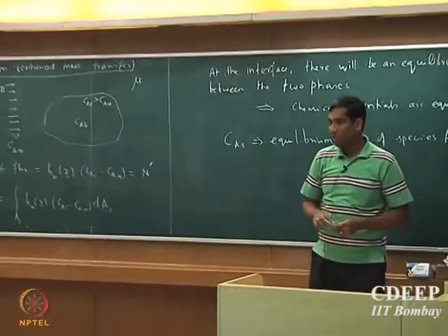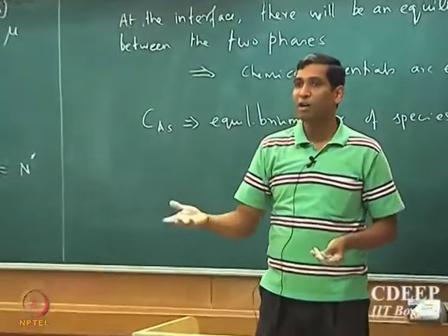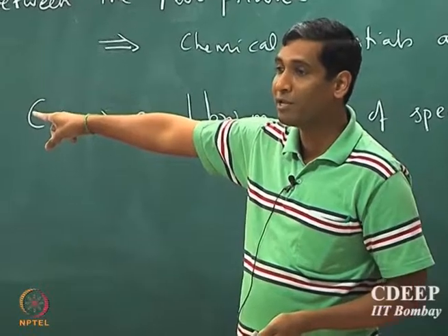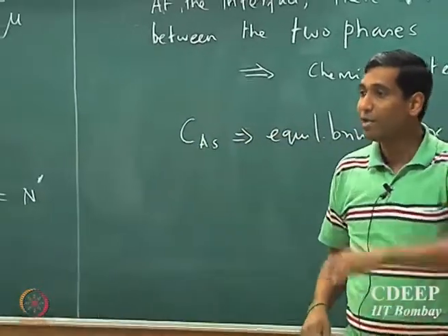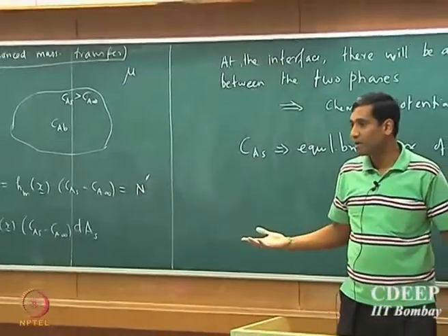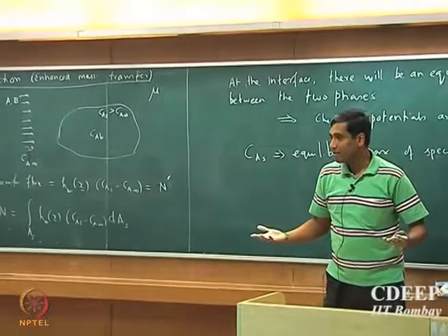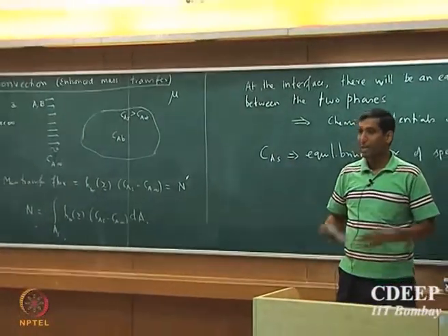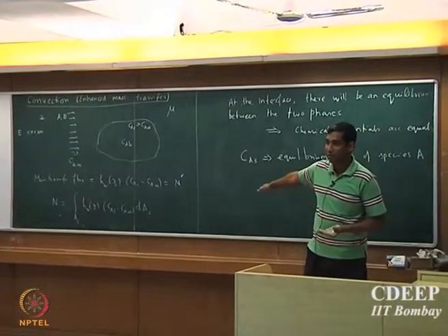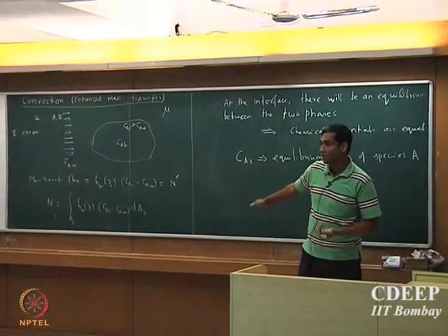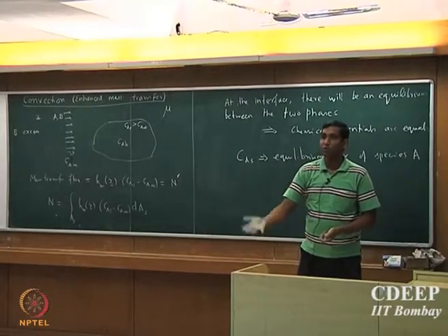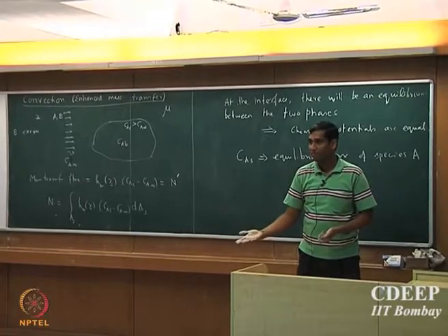Right, if you assume the heat transport case, the question is, will there not be a temperature gradient? So note that I said it's a well mixed system. So CAB is the bulk concentration everywhere. Similarly, if you assume that it's a well mixed system where the temperature is uniform, it's the same scenario. The only difference is that there the system can take more energy and it will lead to an increase in the temperature. That's not the case with mass transport. There is an upper limit on how much you can pump, and that is based on the solubility of that species in that medium.